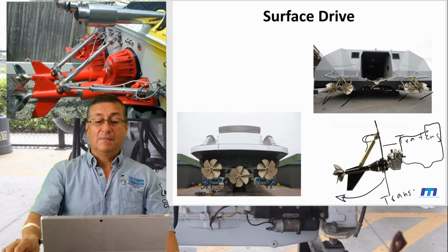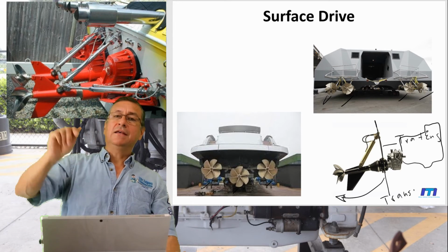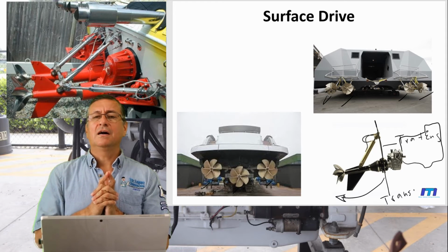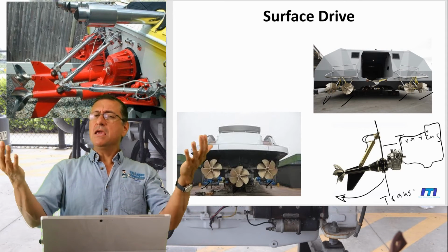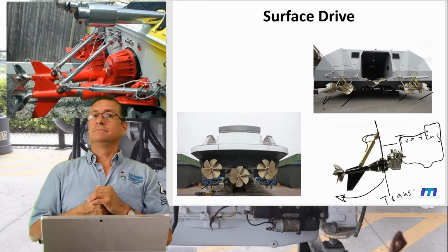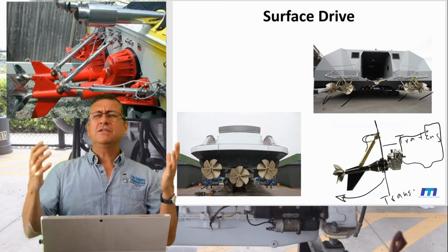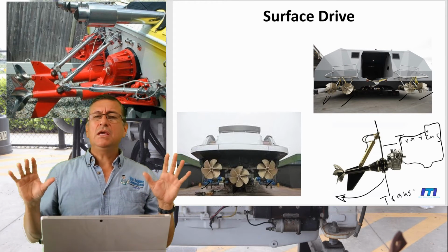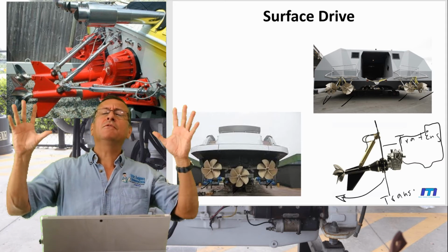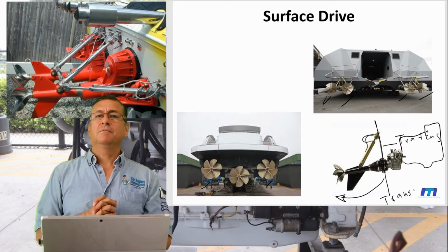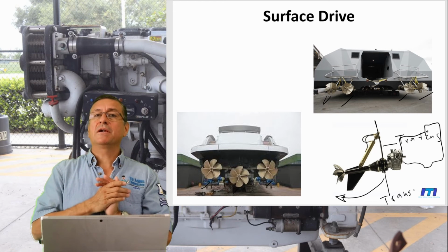What is the advantage? You can put the propeller outside. You remember in our intro course, in a typical inboard boat with inboard propeller, what is the number of blades normally for those boats? Normally it is 3 or 4, maximum 5 in some designs, but no more than 5, because you produce overlap, you remember?